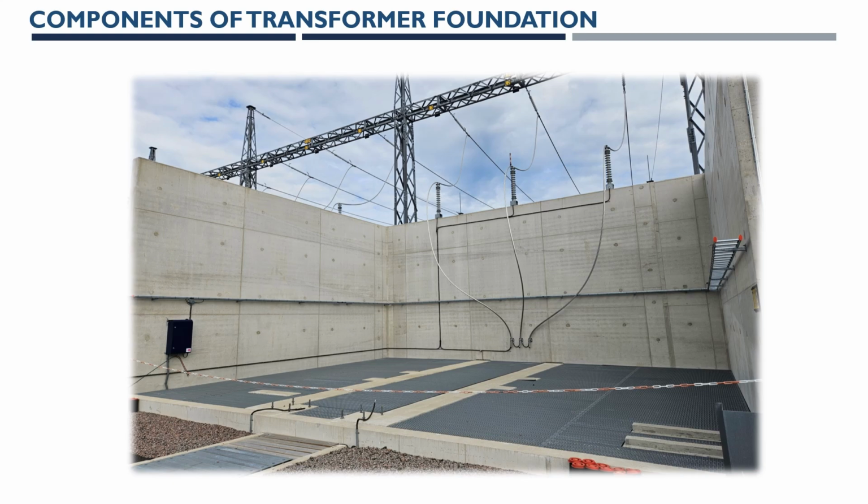So this is a precast concrete element which is surrounded as a firewall to the transformer. So this precast wall, circumferential precast wall, is also seated on the transformer bund. So this is a transformer bund wall, and these are the transformer hauling walls with the jacking pad on both sides for lifting the transformer, for ease of moving the transformer front and back.